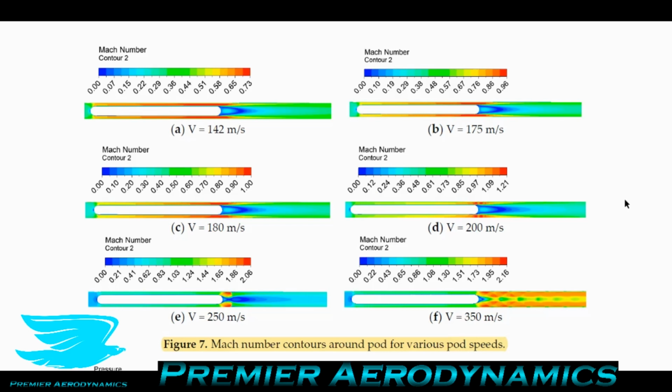At the trailing part, you can see the wake, and that's fairly continuous at the moment at 200 meters per second. But around the wake, where the faster moving flow is, you get regions of very fast moving flow, then regions of a little bit slower flow. So there's this non-uniformity to the flow around it, where you have really not very good mixing of the flow properties, as we mentioned before, because we have shock waves forming. Information cannot propagate through these shock waves, so the flow parameters cannot equalize. So you can't have the same flow velocity right next to each other, because there's this shock wave dividing these two parts.